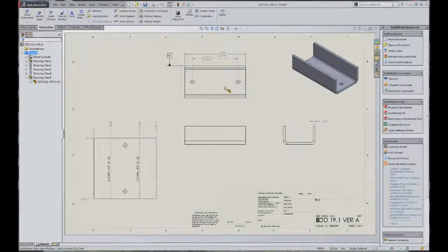sometimes the scale of the whole drawing might get a little bit shifted, okay? So by giving an overall length of the blank, and your dimensions, especially in your 3-view drawing, those guys can then open up and say, hey, I'm going to measure from this line to this line now that I've imported it into another software. Popular software for sheet metal is called TOPS. I'll bring it into TOPS and say, oh wow, this dimension came in at 6.613 instead of 6.813. So it messed with the overall scale ever so slightly.